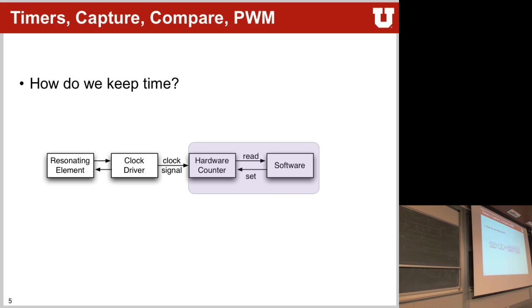This is count. It will count up to the value stored in CCR0, and then it will go down and start again. Go down, start again. Okay? While the time from here to here is 0.5 seconds. Sorry, this is a little tiny. Running out of space.